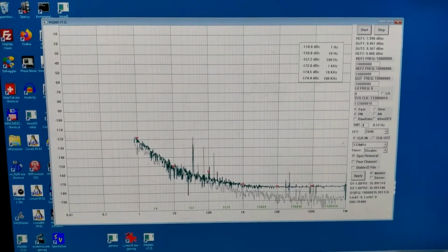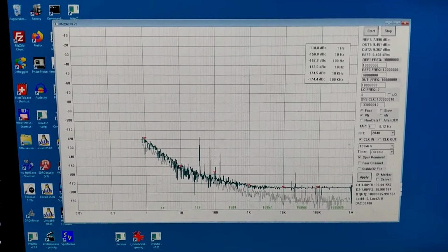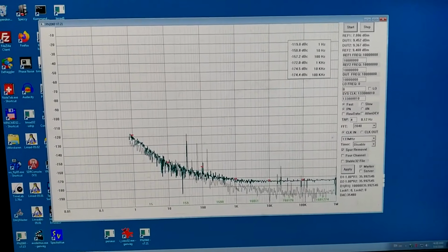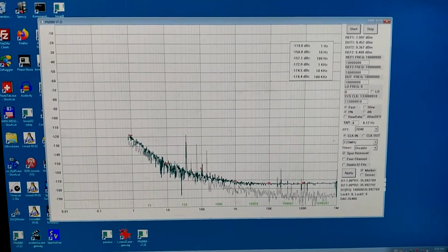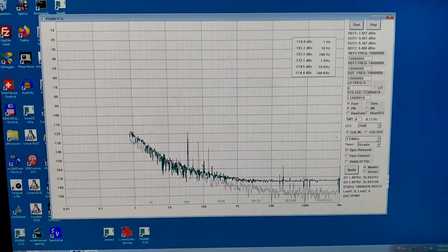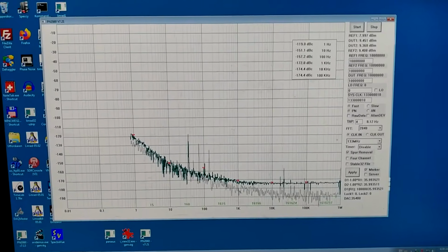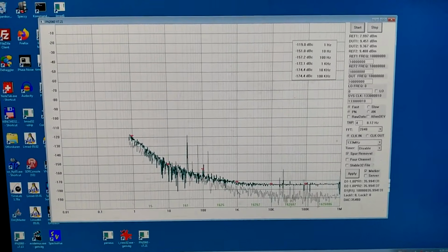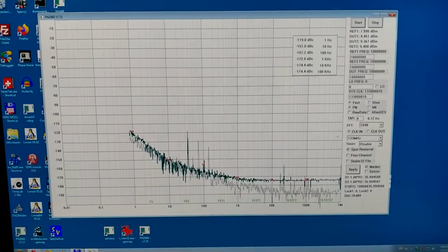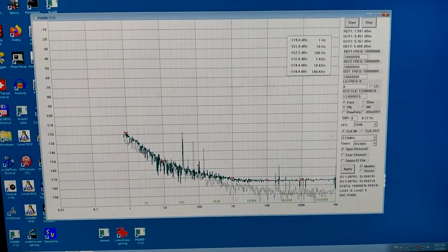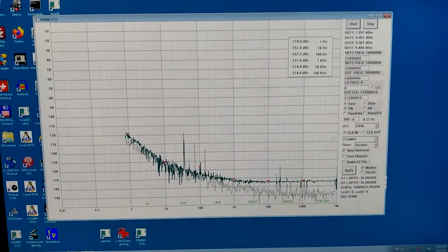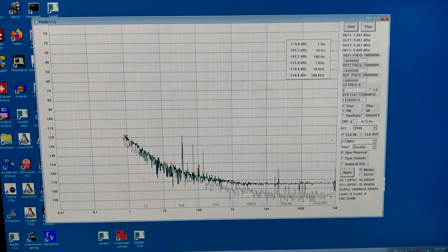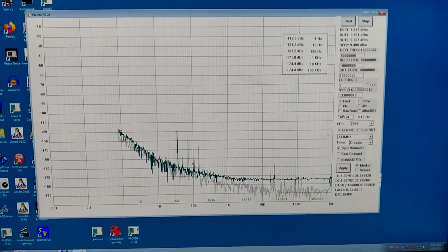I'm still using the second version of the crystal filter with the transformer sending current into the crystal. Frequency is now about 70 Hz higher than before, and the phase noise looks normal. I will modify the frequency shifter for the rubidium oscillator to shift the frequency upwards instead of downwards, because the performance I see here looks similar to what I had when it was running at the Wenzel frequency, which is 35 Hz below this frequency.